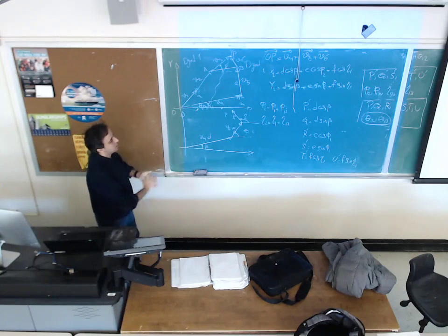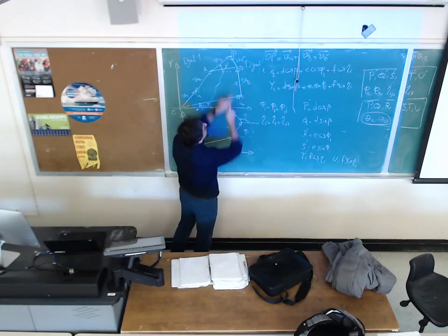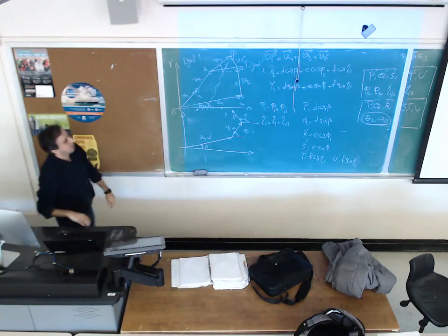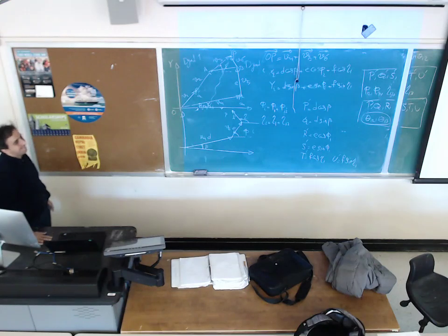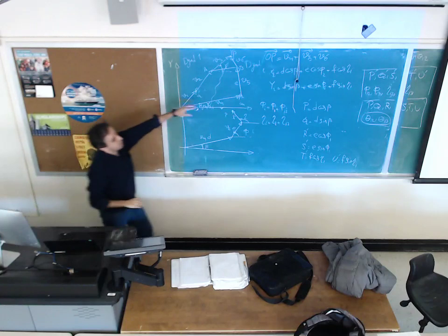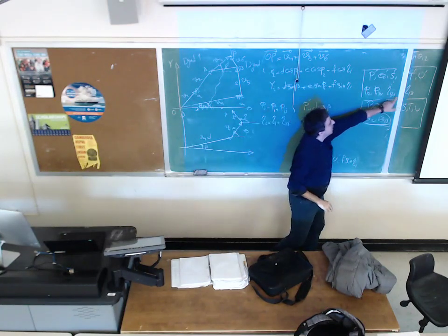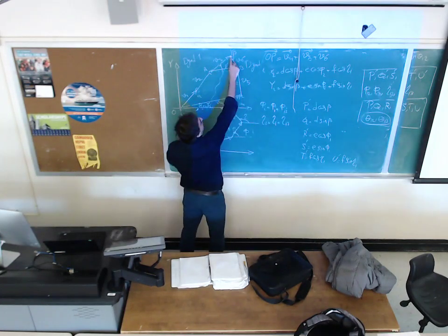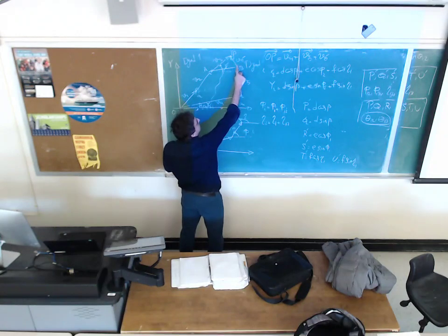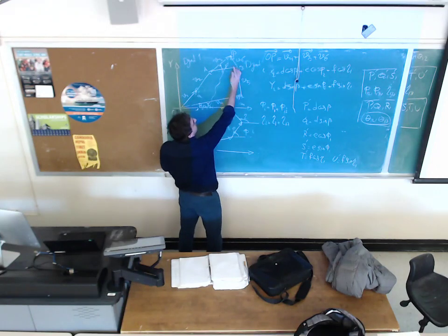What is eta_12 and eta_13? It is the rotation of this length from the first precision point to the second and from the first to the third. So this line is a part of the rigid body, and this line also is part of that.